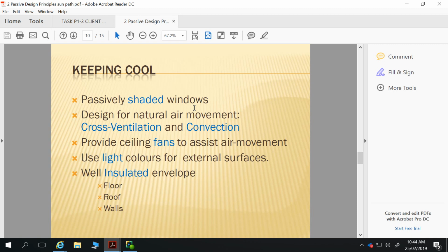The way insulation works is it's about separating elements that would conduct heat, with lots of air in there to stop heat being conducted. As soon as we squash it down, we make it far denser and we reduce its ability to stop those heat flows.